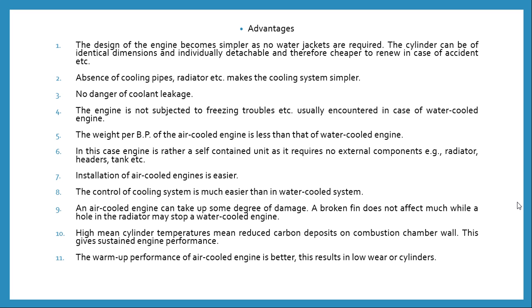A high mean cylinder temperature reduces the carbon deposit on the combustion chamber wall, and this gives sustained engine performance. The warm-up performance of an air cooled engine is better. This results in low wear of the cylinder.